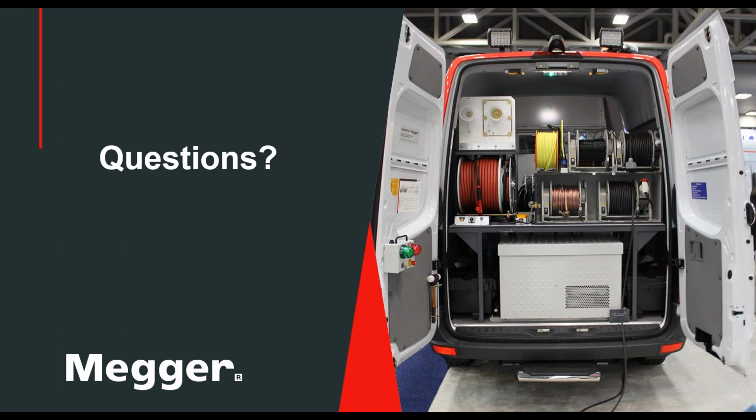All radars can only see the cable as one long footage as opposed to footage breakdown at each point. So I'm assuming he understood that already, which is why he's asking about practices. But some middle point that you can isolate from would be the very best method. But if you do not have that ability, try from each end. And I know it'll be a little time consuming, but depending on where that fault is, if it's close to your connection point, your odds have increased with the radar, the arc reflection showing you footages. Hope that answers that. If anybody wants to add, that's fine.